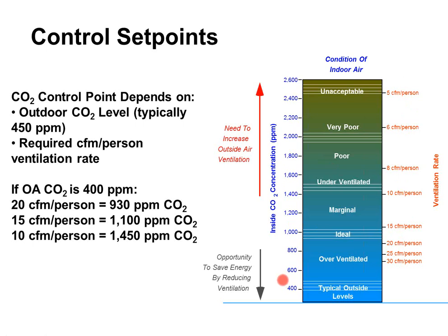In fact, the CFM per person that's in the codes, I don't remember if I said this last week or not, but the CFM per person that's in the codes, those numbers in the tables were originally backwards calculated from CO2 study data back in the 1980s. That's where those numbers had evolved from. So it's not a new idea at all.